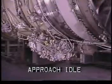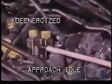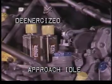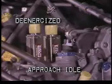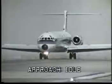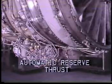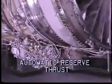Approach idle is the alternate idle mode. Placing the aircraft in the approach configuration de-energizes the idle solenoid, causing an increase in idle N2 RPM. This higher idle RPM setting ensures the engine can meet rapid acceleration requirements during approach and initial touchdown. The final input to the fuel control is the automatic reserve thrust signal, or ART signal, which, when generated, is sent to this solenoid.